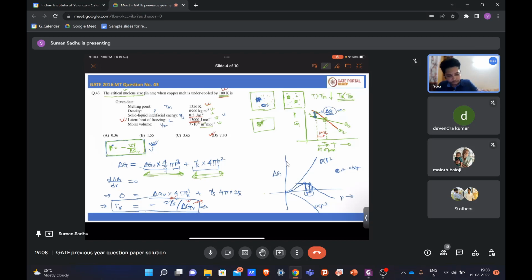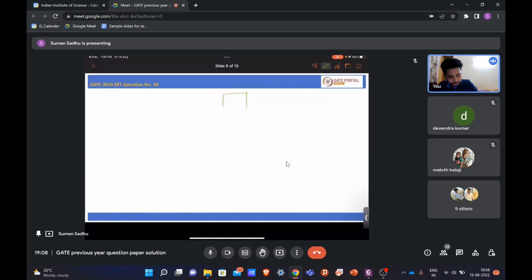So, like you have liquid in this chamber, right? In liquid, atoms are randomly moving here and there. In liquid, the atomic arrangement is not regular, right? But when you are solidifying, this is becoming regular, right? So how is it exactly forming that regular arrangement? In liquid itself, it is not totally random, you can say. In liquid, one atom, two atoms, in some small region, are arranged in a regular pattern.